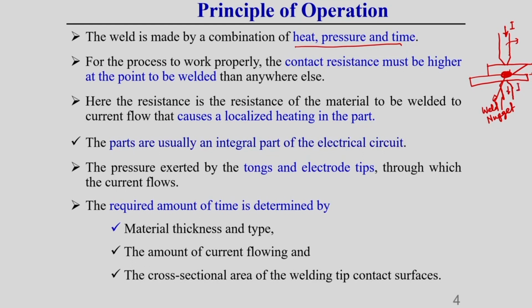Now this electrode is connected to the power source. Due to this current flow through the electrode, workpiece and this contact region, there is a series of resistances, as you can see. Wherever there is resistance due to current flow, there will be some heating, correct?